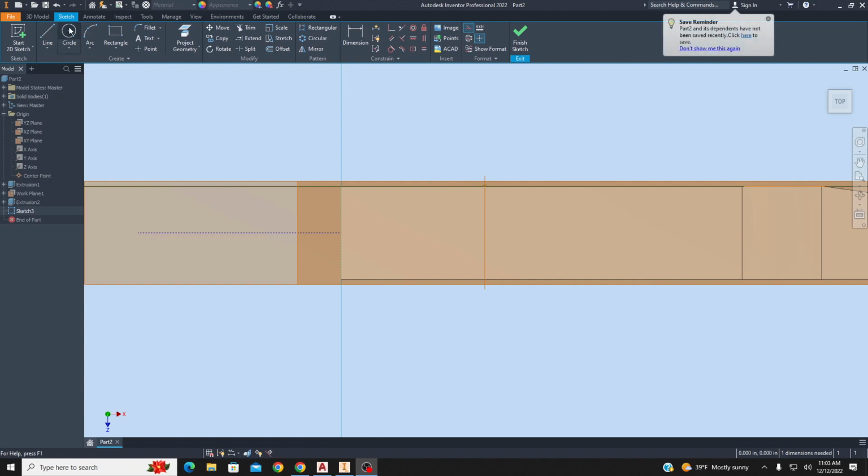and then we're going to draw an arc here, 1, 2, and along that line 3. Nope, we made that construction, so we're going to make it not construction by selecting it and unchecking construction. And then we're going to give this a dimension of 5/8 in radius. There we go. See, that flattens it out quite a bit. But because we lined up on this center line, it maintained the center point of that arc in line with that center line. If this point were way up here or way over here, we'd have an uneven arc.